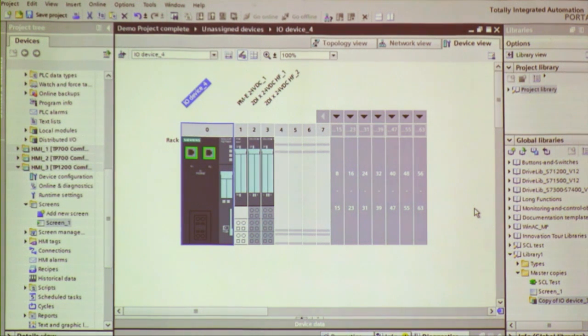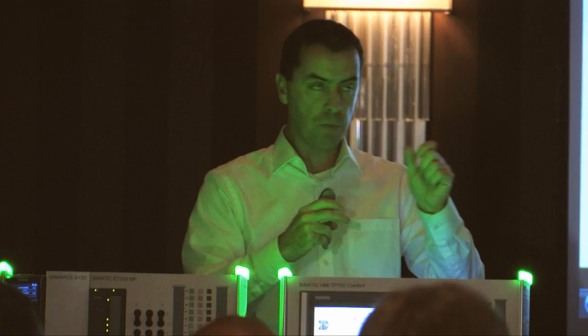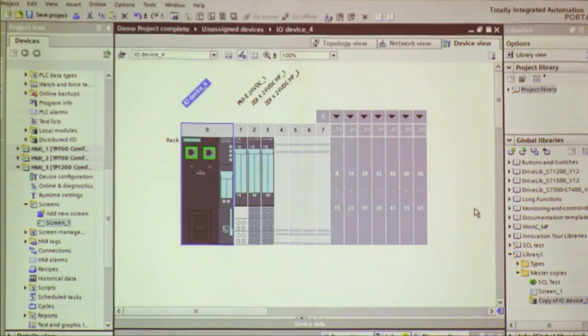And this is very, very handy. A good example is safety, right? You configure a safety I/O card, and it meets the exact SIL safety regulations it needs to meet. You parameterize it in the properties. You put it in the libraries. It's good. It's got the stamp on it. And therefore, anyone else reusing that, your colleagues, can just pull that out of the library, and they know, okay, this is configured exactly the way it needs to be.